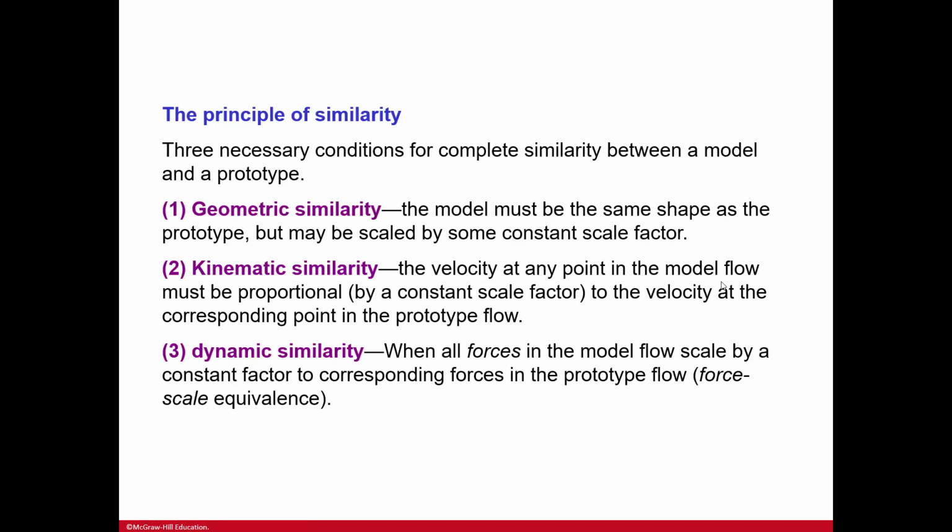Here's the principle of similarity. So you have geometric similarity. The model must be the same shape as the prototype, but scaled by some constant scale factor. So you can see 1/10 scale, 1/12 scale, 1/5, i.e. whatever is appropriate for your experimentation.